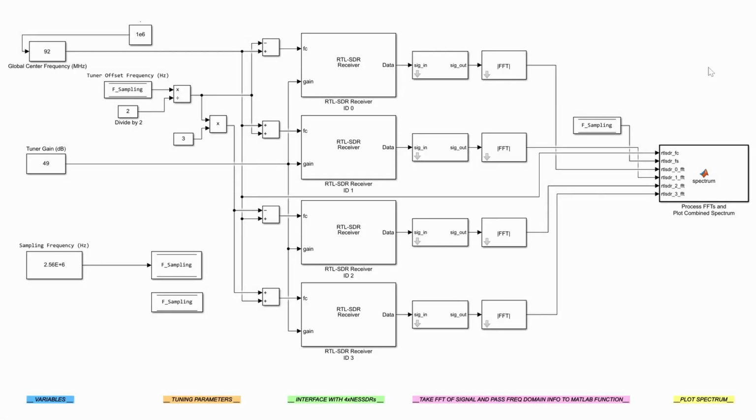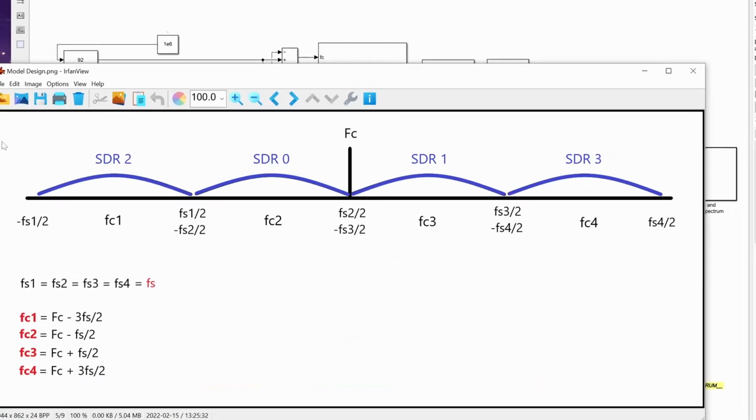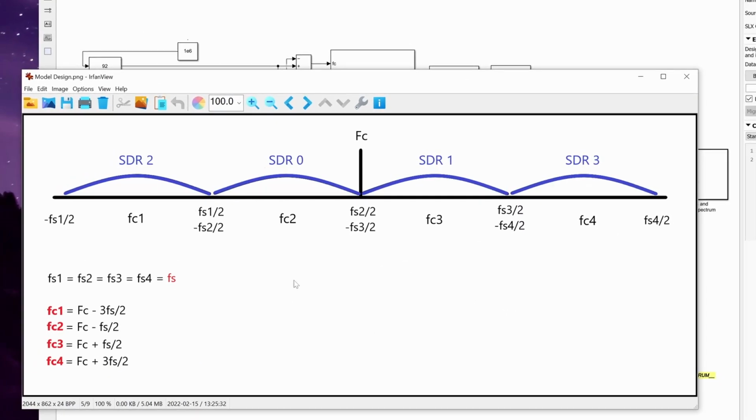Now notice that the 4 SDRs are identical in terms of the instantaneous bandwidth each one is providing. Therefore, they would look sort of equispaced when the bandwidth is aggregated, and this is shown in this figure here. This makes the aggregation process a little easier since they share the same sampling frequency variable, which is Fs right here in red.